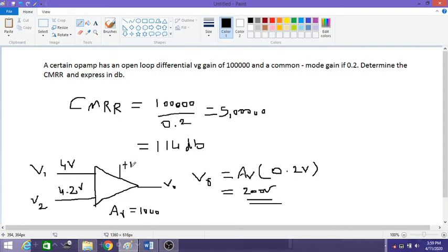If I have connected say 15 volts or 24 volts, that is the maximum that I will get. But I'll not get exactly 15 volts, I'll get approximately that, because the output voltage depends on the load resistance. The higher the load resistance, the closer I'll reach to the reference voltage. So that is the meaning of the output voltage swing.